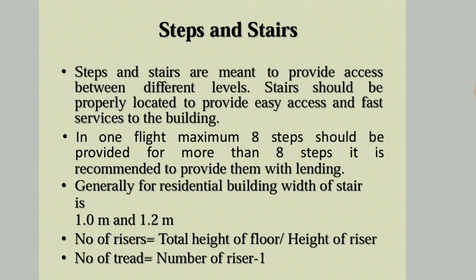Next, the last one, steps and stairs. Steps and stairs are meant to provide access between the different levels. In order to provide access for the building, we are going to lay these steps. Similarly, in order to provide access to the next level or the first floor, we will be providing these stairs. Mainly, in one flight, a maximum of 8 steps should be provided. For more than 8 steps, it is recommended to provide a landing.